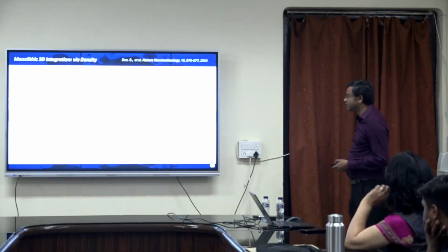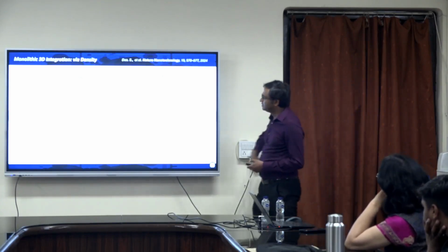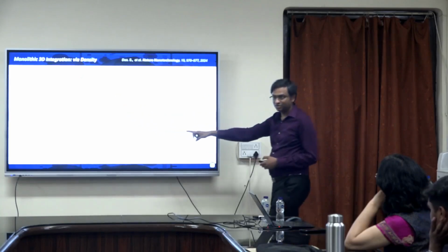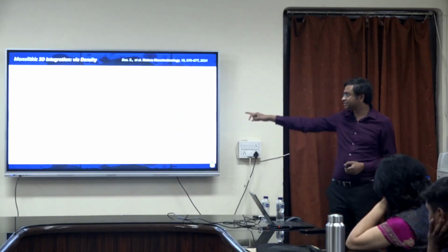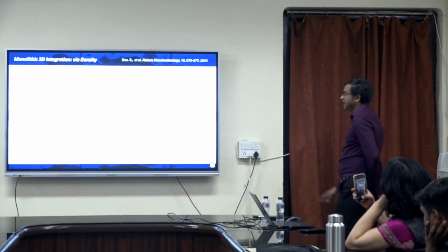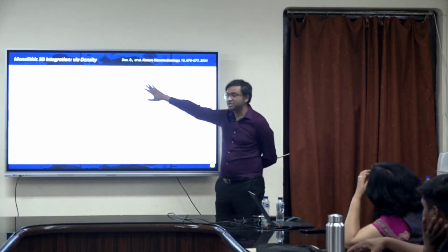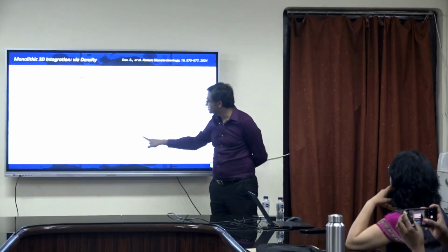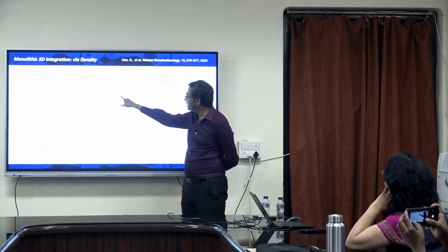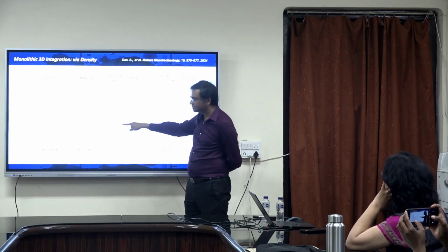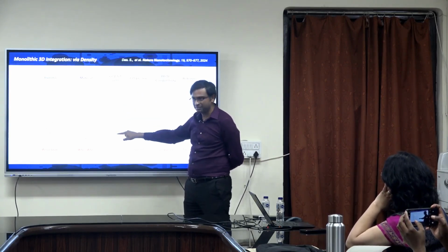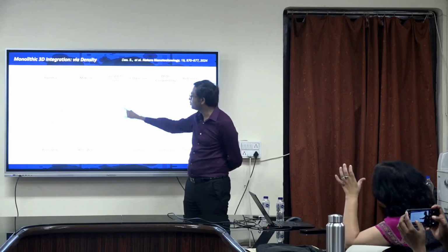And here you can clearly see that this is where we are competing not with academic institutions anymore. We are literally head on with the industry. And these are all through heterogeneous integration, packaging technology. You should be looking into this number, this via pitch. You see the via pitches are of the order of tens of micrometers. Very recently IMEC, just last year, has introduced one.